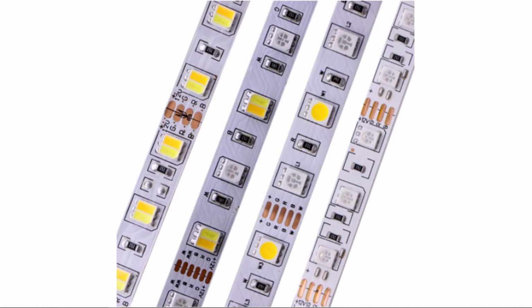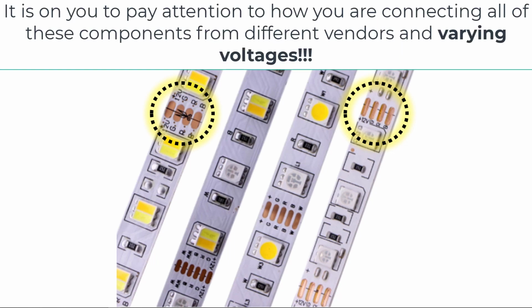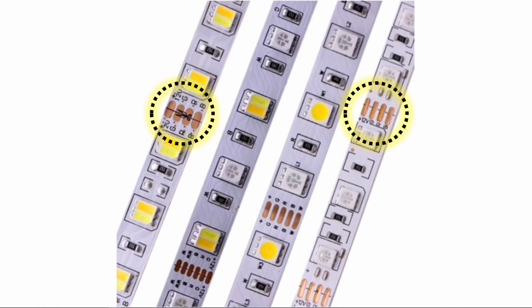Here again is a couple examples of different LED strips. Take note that on the cut lines here, you've got plus 12 GRB. Now, why is it GRB instead of RGB? They call these things RGB, but they're all manufactured GRB or BRG, whichever way you want to say it. Now, these are two different strips here. The upper one looks like it's a combination of two different types of LEDs to give you your RGB. The second one is a combination of both.